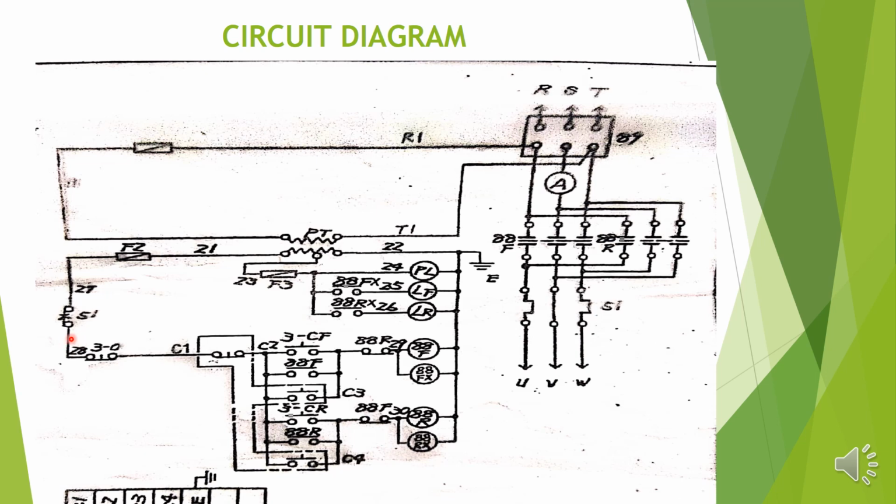You can check by multimeter, 95 96. If not closed, it means there is some problem in the motor, that's why the motor is getting tripped. So this is the stop push button from the local panel, and you see that this C1 is also a stop push button, but this is the remote box. You see this box, all these switches are inside.